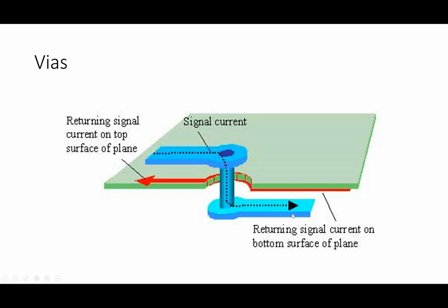We try to avoid it as much as possible through careful layout, but if we need to do it, we need to do it. All right, all boards have these things. We just do our best to try to avoid them as much as possible through careful layout and routing. Okay, so one thing about these is although they do have a ring around them, that ring is usually much smaller since we don't need to be soldering to those particular components.